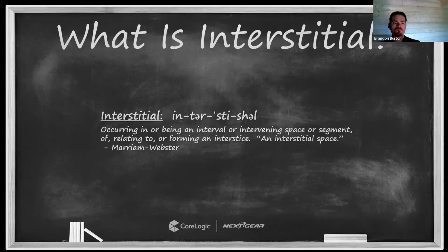And that's part of the reason why this becomes so critical, because when we go in to dry a building, 99% of the resources that we typically deploy, if not 100% of the resources we deploy, do a great job of accessing everything that you can see, right? If my eyes can see it, then generally an air mover can impart air on it. And if an air mover can impart air on it and create circulation and velocity, then the dehumidifier in that space is also going to affect it, right?